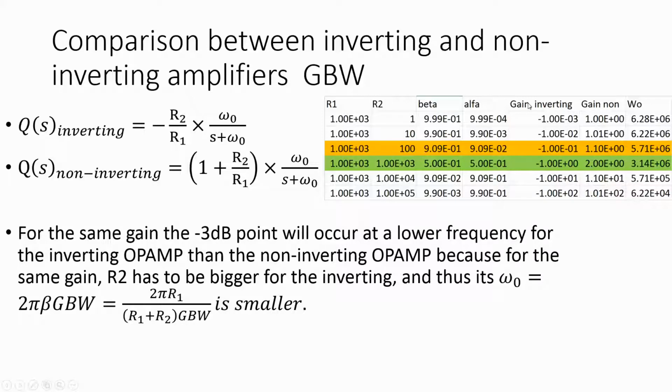So the gain of the inverting op amp is just this times that, this divided by that, taking the times minus 1. So it starts off less than 1, right? And look at where it hits minus 1 or 0 dB. Look at omega naught. It's a little bit above.